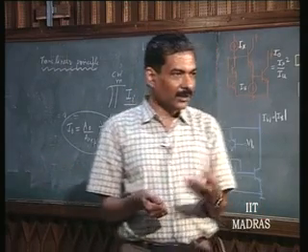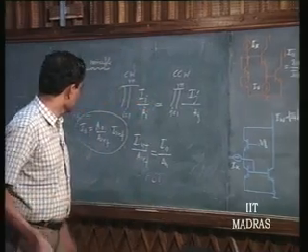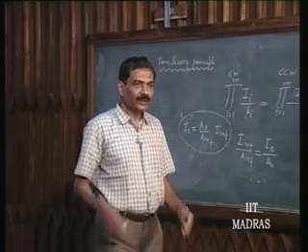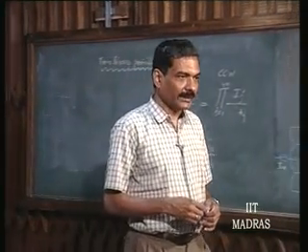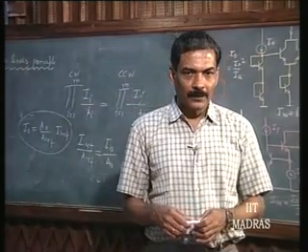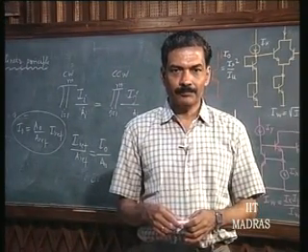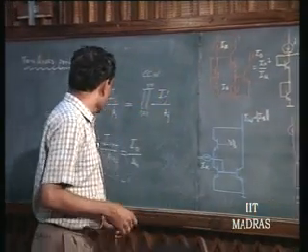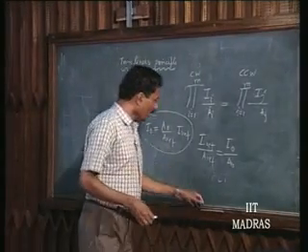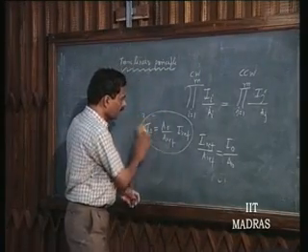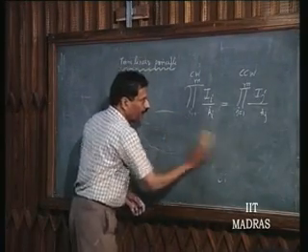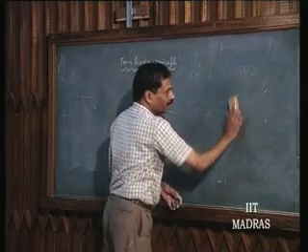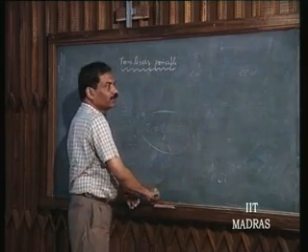Therefore, this is a technique of obtaining different current ratios by using different areas for the devices. Is this clear? So, this is part of the current mirror aspect, but we are trying to extend this principle to more general things.